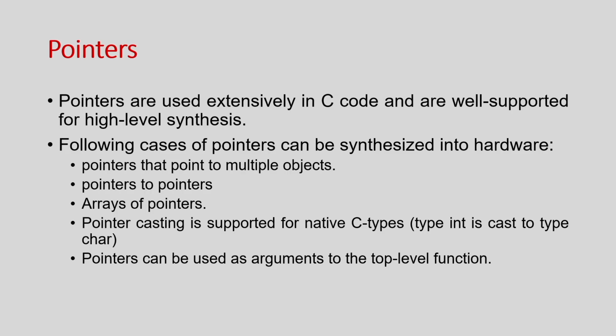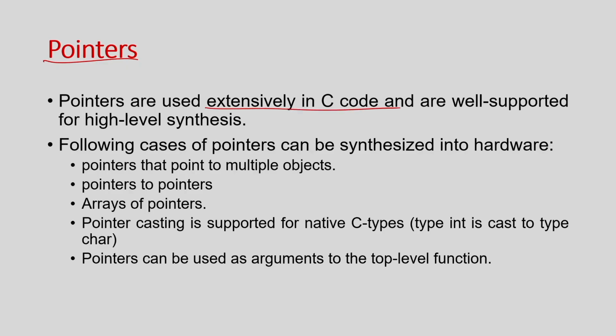Okay. So, now I move to the discussion on pointers, and we know pointers are a very important functionality in C through which I can access the address of a register or an array or a variable, right. It is extensively used in C and it is actually very well supported in high level synthesis, right. If you look into a pointer, what is that? It is basically you are accessing a location, right. So, in hardware, if you think about it, you have an array and you are accessing it through a pointer, which is nothing but you have a RAM and you are accessing it through some address, right.